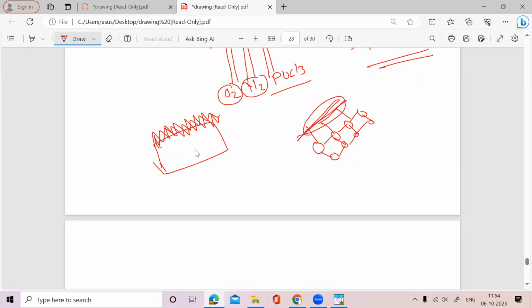So when an electron-hole pair is generated, the electrons can come onto these dangling bonds, and we can lose some electrons and current also. For this reason, passivation is needed. In the start of my talk, I told you silicon nitride is not only for anti-reflection coating. It is also treated as a passivation layer. It is a dielectric layer and it will passivate the surface.